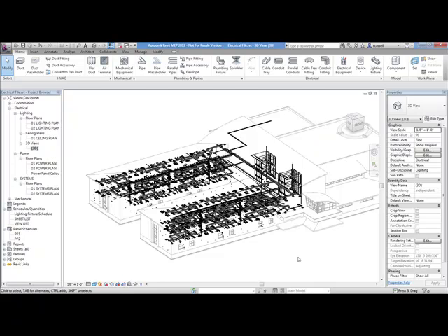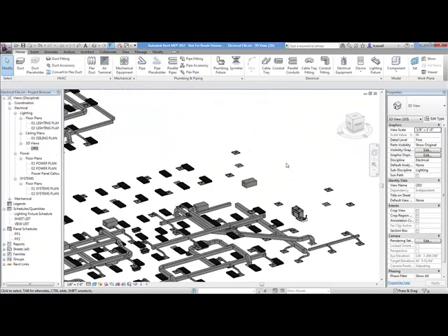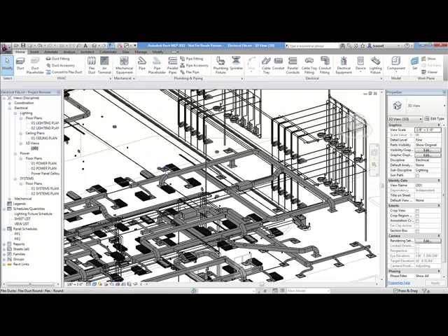Now it makes it quicker and easier to get a complete count of light types that are being used. As you can see in this example, in multidiscipline firms, you can also see that my lights are being placed around a lot of mechanical equipment, plumbing equipment, pipes, conduit, cable tray, and other fixtures that can get in the way. So we can actually run coordination reviews as well to make sure our lights aren't hitting any other objects that they may encounter in a ceiling grid, such as sprinkler heads or air terminals.